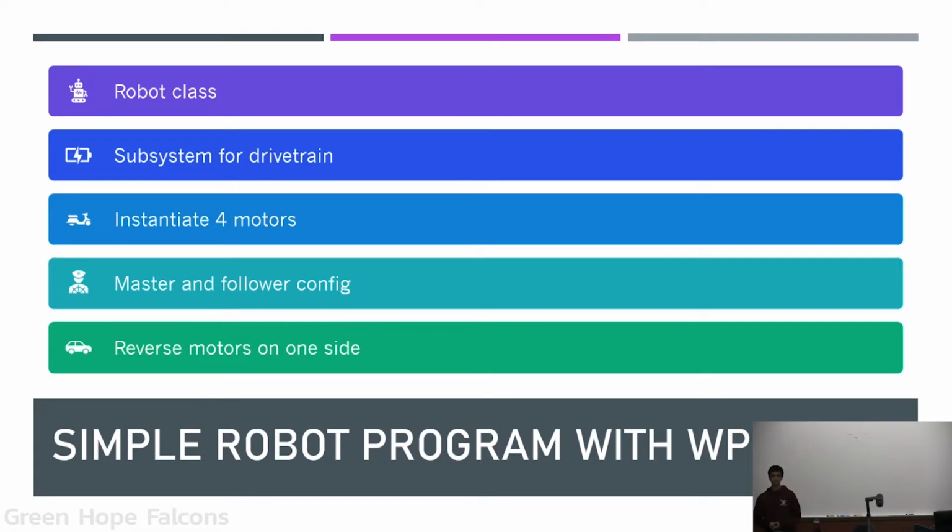So let's talk about trajectory tracking. Does anyone know what this means? What it means to track a trajectory, or path following is another term for it. Does anyone know why it's used or what even it is? Yeah. Would it be like measuring how far the robot has traveled and in what direction so you can navigate the environment autonomously? Kind of. So yes, it uses a lot of field measurements. So it's essentially you draw some curve from point A to point B on the field, and then you follow that curve essentially.